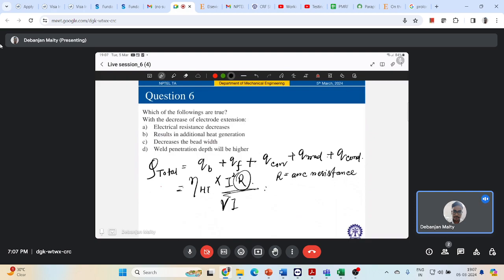So you have to optimize your welding current in a way that it provides all those outputs in a very optimal condition. So my weld penetration should be within some range. My weld distortion should be in some range, so that it doesn't hamper your workpiece, right?